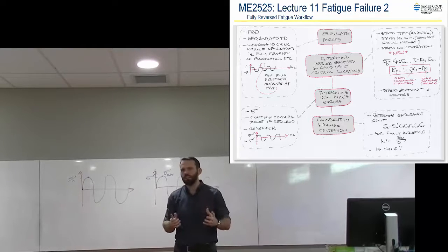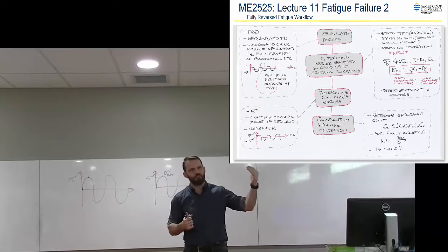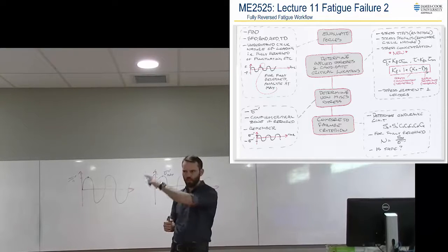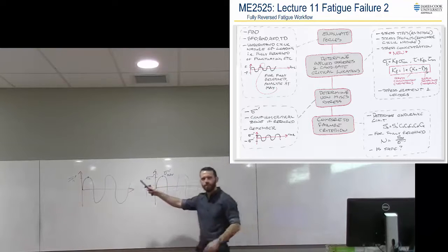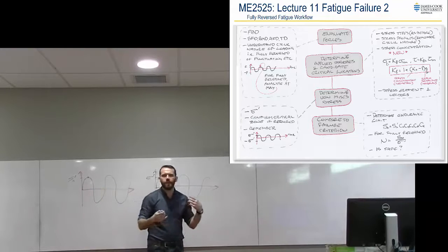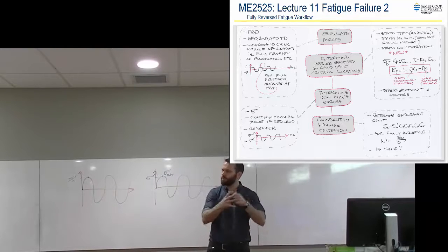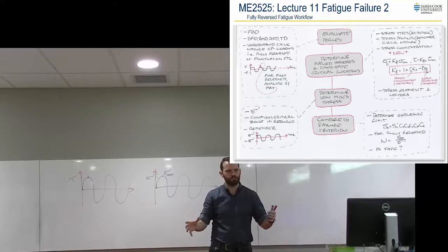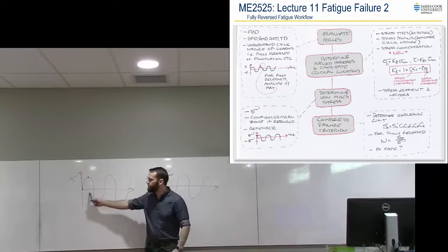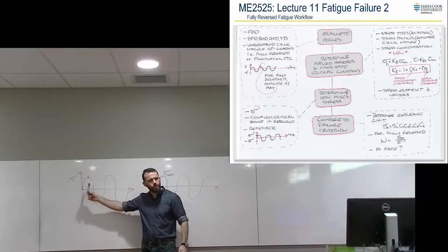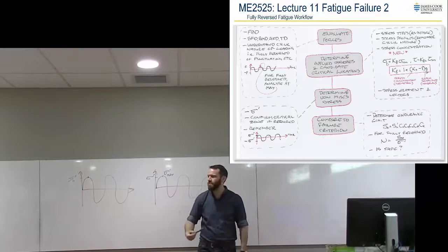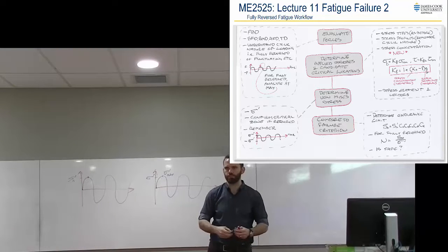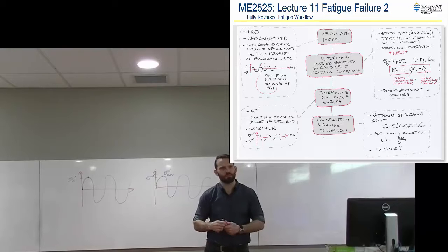Okay? So when we talk about this, even in this very first step, evaluate the forces, we're analysing that maximum force. But that maximum force is representative of the whole time series of force, and then you convert that maximum force to our maximum stress and compare that to the maximum allowable, and that will give you your factor of safety, but it's representing the whole fatigue case. Okay? Because this is measured in fatigue. So when you measure your critical limit in fatigue and you compare your actual applied in fatigue, then it's apples with apples. Alright? So that gets a bit confusing to some people sometimes, so I figured I'd clarify that a little bit.